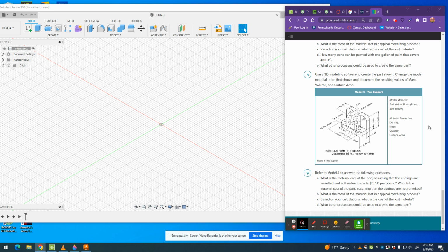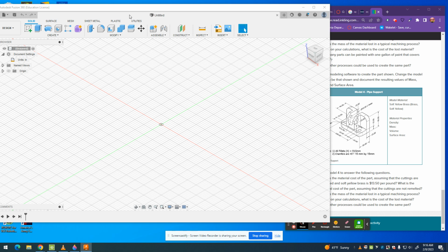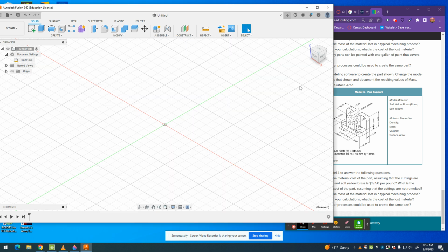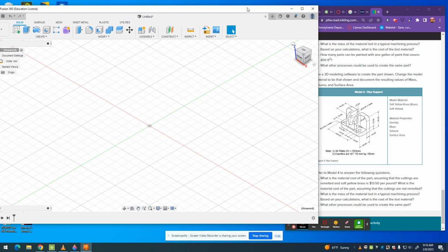So that's the big thing: right away you're going to switch this to millimeters. Oh yeah, the last one's in millimeters. So we're going to hit on the left-hand side here. You see these arrows, and you actually have to click on the drop-down arrow. You can't just click on this. You've got to click on the drop-down arrow, and you're going to hover over this, which is going to bring up your edit tool. Fun times, right? Okay, then click on here and go to millimeters. All right, now we're in millimeters. Now we can just type in the stuff, and we'll be good to go.